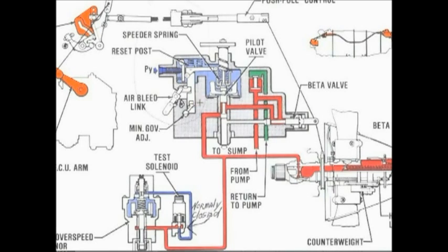Governor is working towards that objective of keeping a constant speed on the propeller. Under normal flight conditions, the governor acts as a constant speed unit and maintains the propeller speed selected by the pilot by varying the blade pitch to match the load to engine torque in response to changing flight conditions.